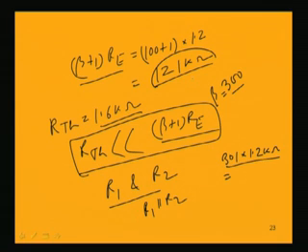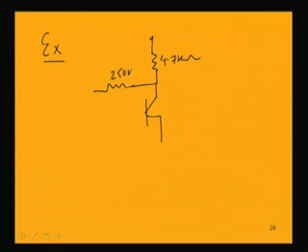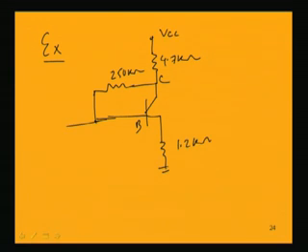Now, this is the potential divider biasing scheme, and if we now consider the collector feedback bias scheme, suppose we have a scheme using collector emitter feedback bias: this transistor having this 4.7 K, here 250 K, with this collector point fed back to the base through this 250 K resistance, and we have this 1.2 K. In this case VCC is 10 volt.